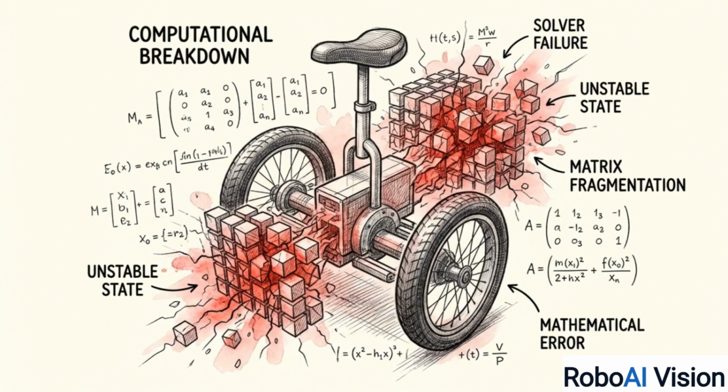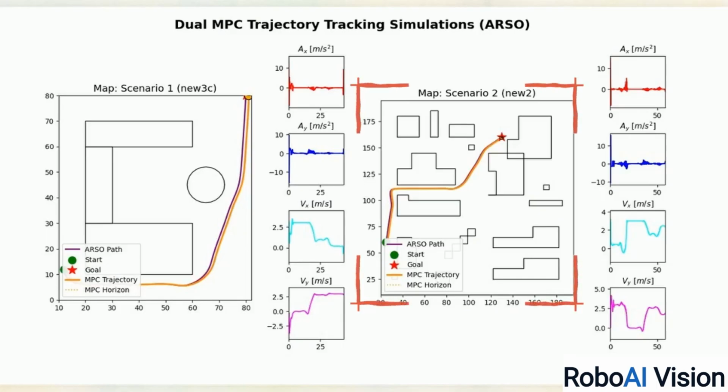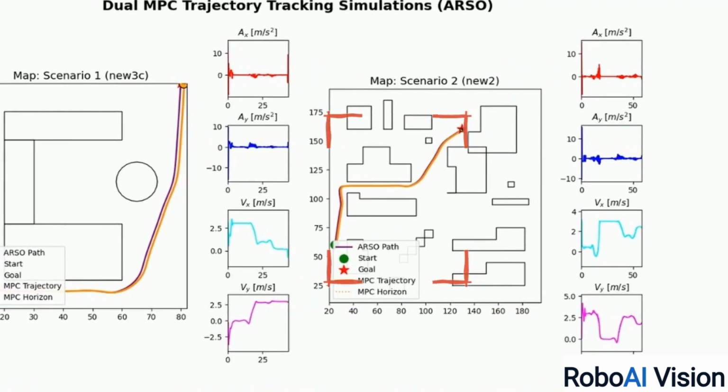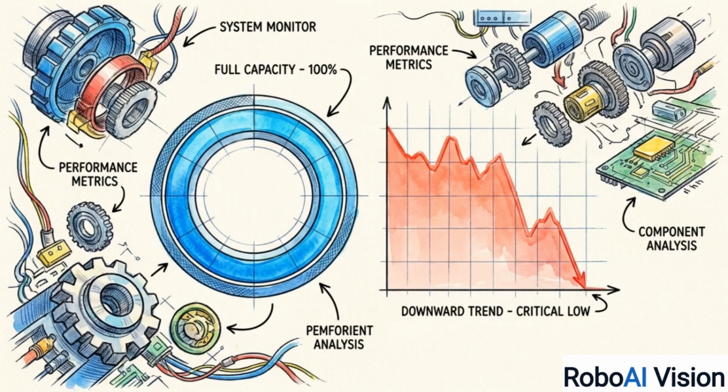These final simulations show the complete synthesized pipeline operating successfully in dense environments. The initial search routes are smoothed to physical feasibility, and the controller correctly bounds the acceleration and velocity kinematics within the machine's strict mechanical limits. Integrating a memory retrieval system and B-spline interpolation yields a 9.3 times planning speedup and drops tracking errors by nearly half compared to standard baseline systems.